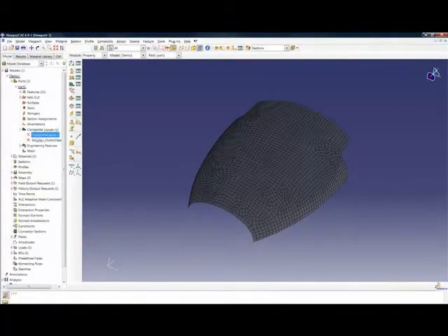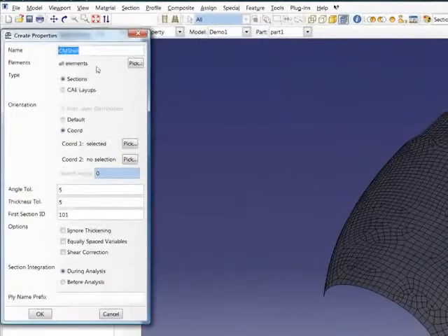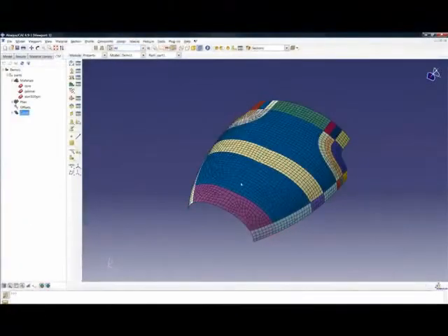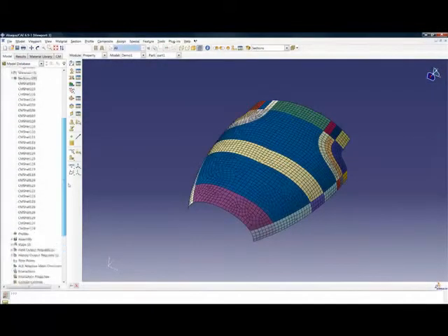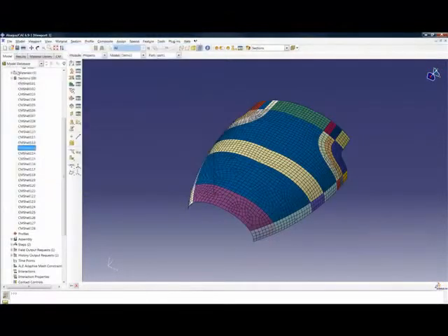If we now go back into the Abaqus application, you can see there's some additional information has been created to reflect the fact that we have started a Composites Modeler model, and then we can create typical Abaqus sections, composite sections, using that information from within Composites Modeler. We can do that fairly simply here, just accepting the defaults, and as you can see, because we had sections displayed, we can see the extent of those, and through the menu here, the browser tree, you can see all those plies have been transferred into a number of sections.